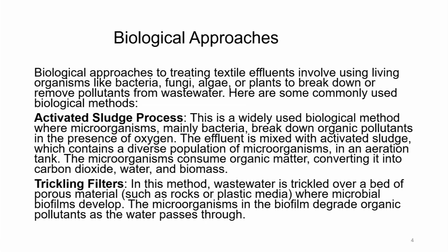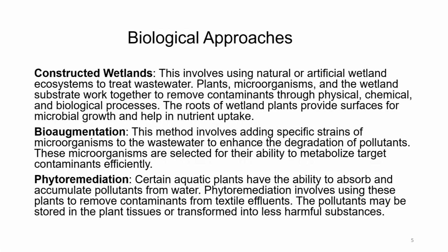Trickling filters. This also we have studied in the previous lecture. In this method, wastewater is trickled over a bed of porous material such as rock or plastic beads, where microbial biofilms develop. The microorganisms in the biofilm degrade organic pollutants as the water passes through it.